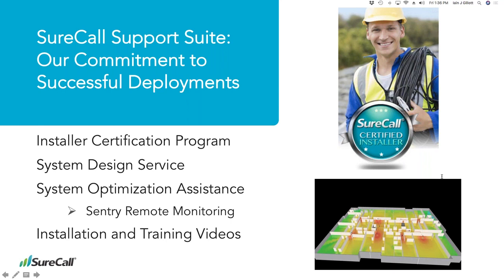You'd be able to make a call. Typically, when we design a system, we want complete coverage throughout the office or the space. So you shouldn't expect any sort of degradation, especially in voice calls. If you have negative 100, negative 95, you're still going to be able to make that call. That's probably what would be in those green areas. It depends on the strength of the signal coming inside, but at the red nodes you'd be really hot with signal. In the green, you'd have enough to make a phone call. If it wasn't, we'd put in more gear or more antennas, or reorient the antennas to make sure we get coverage in those spots.